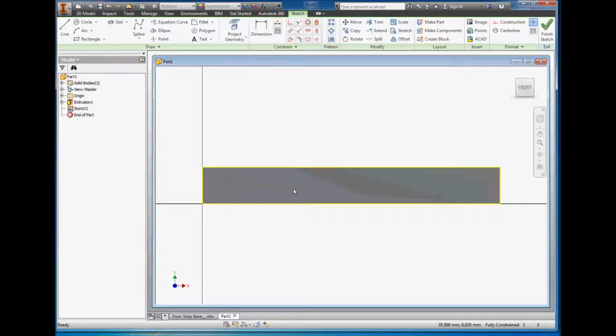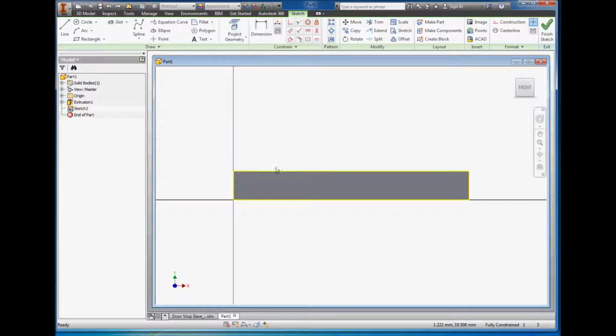So we're sketching directly onto that surface. This yellow rectangle is an offset from that particular face that we chose to create a sketch on. Now, it's there because we need a reference geometry where we can draw a new shape. I'll quickly demonstrate. If I click on one of those lines and delete it, now it's gone. It's only got 3 lines left.